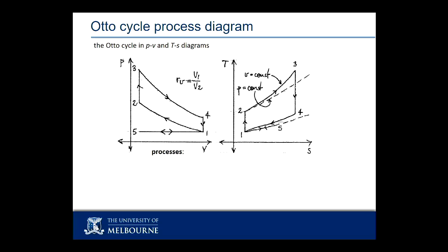And down it comes. This compression and expansion, the best possible compression and expansion I can do is isentropic, which is to say adiabatic and reversible. So these are isentropic compression, isentropic expansion. If they were on a TS diagram, they'd be isentropic compression and isentropic expansion. We've just looked at constant pressure lines on a TS diagram.